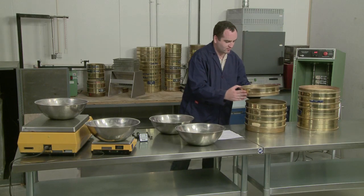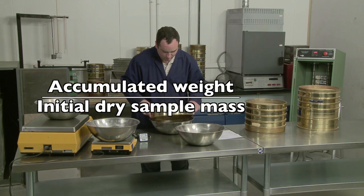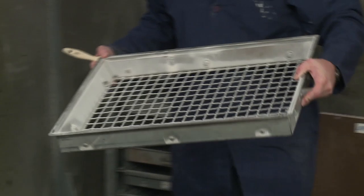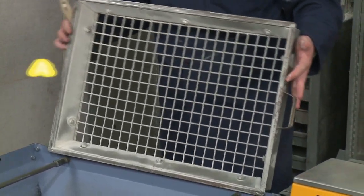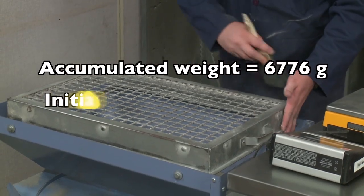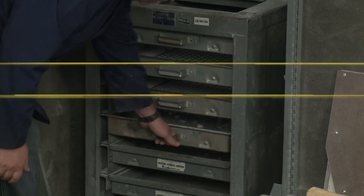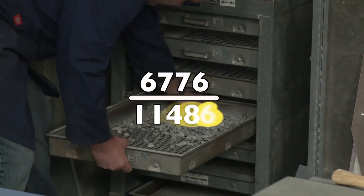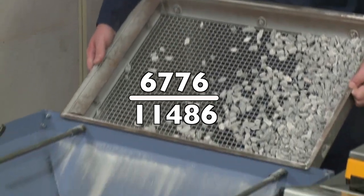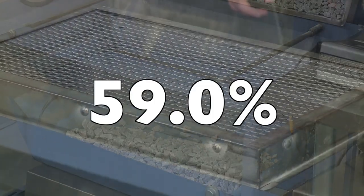To calculate the percent retained on a sieve, divide the accumulated weight by the initial dry sample mass and multiply by 100. For example, if the accumulated weight on the half-inch sieve is 6,776 grams and the initial dry mass from T11 is 11,486 grams, the percent retained is 6,776 divided by 11,486 times 100, which equals 59%.